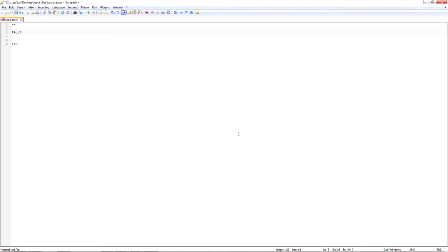First, we want to define a fault. This is done in the data group faults. We name the fault F1. It should occur at bus 7 and be a three-phase to ground fault.